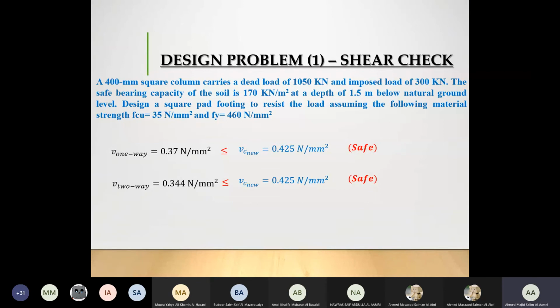Now what will happen if I change the scenario? I kept two books on one side and one book on the other side. Which one is going to be harder for you to bend? The two books. So now you can see that by increasing the depth, you will reduce your deflection. By increasing the depth, it's going to be harder for you to bend it. It means that it's going to deflect less. Are we okay? Are we fine about the concept of the depth? Is it clear?